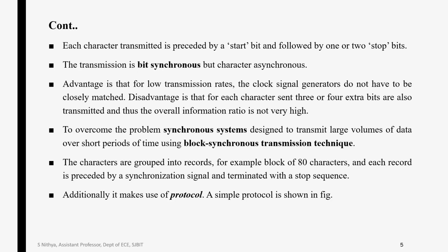Each character that is transmitted is preceded by the start bit and followed by one or two stop bits. So the transmission is bit synchronous but the characters are asynchronous. There are some advantages, namely a low transmission rate.